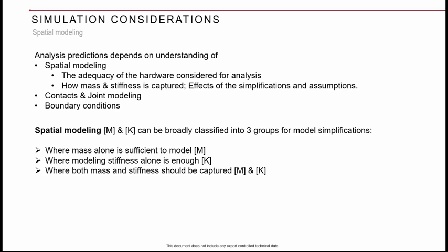Yeah. Like Akash mentioned, it is definitely about understanding the efficacy of the design against the excitation levels, whether it is random or harmonic, whatever excitation you have. What is my response to that excitation, and whether the fatigue performance is sufficient to take it to the field or the testing.